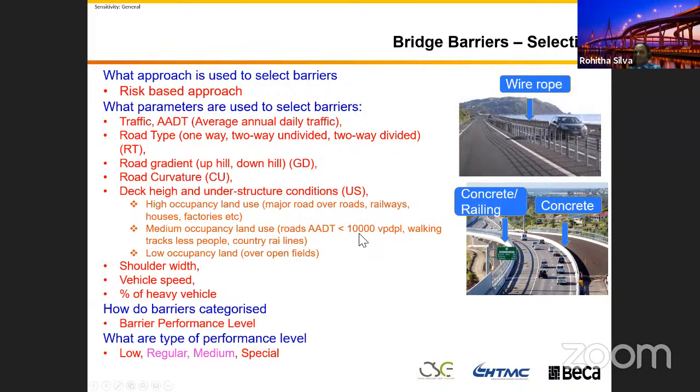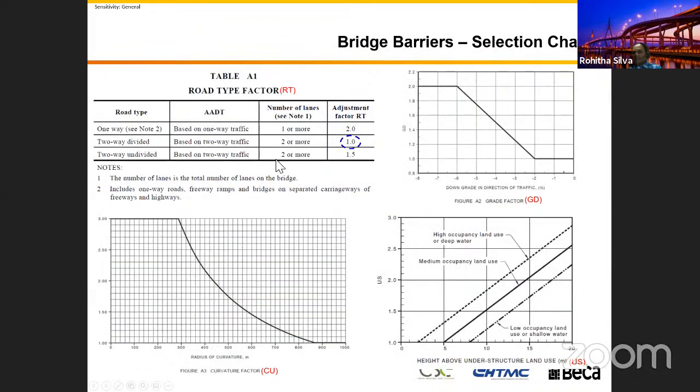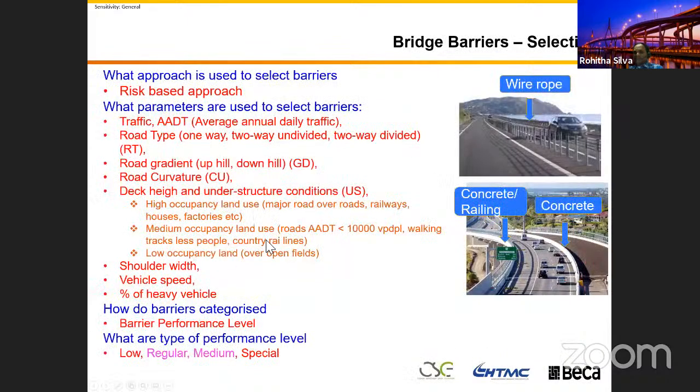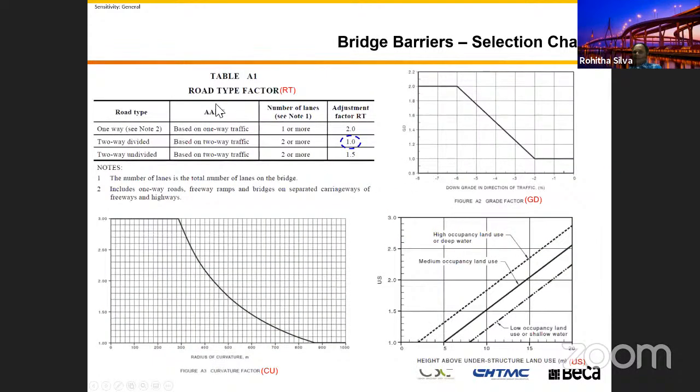And then, as I mentioned, we correlate everything together and convert it into the average annual daily traffic per day. What we use in our normal traffic modeling, that value we magnify using these factors and the correlation between the factors.